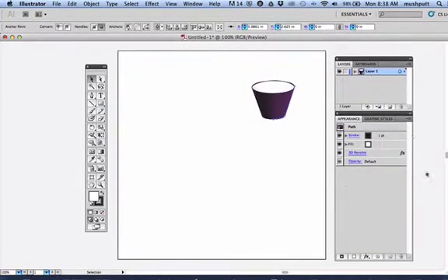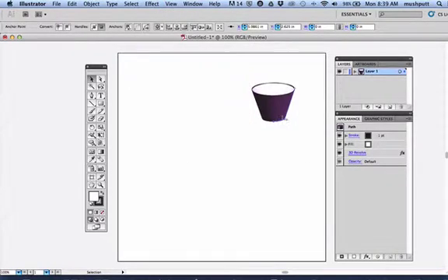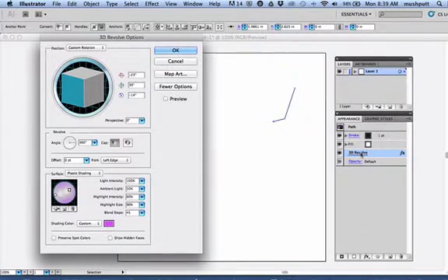And if you'll notice over here in Appearance now, we don't just have the stroke color, fill color, and opacity. We now see 3D Revolve. 3D Revolve was applied. So if I want to go in and make any more changes to the 3D effect on this shape, I edit it through Appearance. If I go back to Effect and click 3D Revolve, it adds another instance of 3D Revolve, and what happens is your computer will slow down and it will become very difficult to complete your edit. So instead, we go back into the 3D Revolve already applied, and we make changes in here.